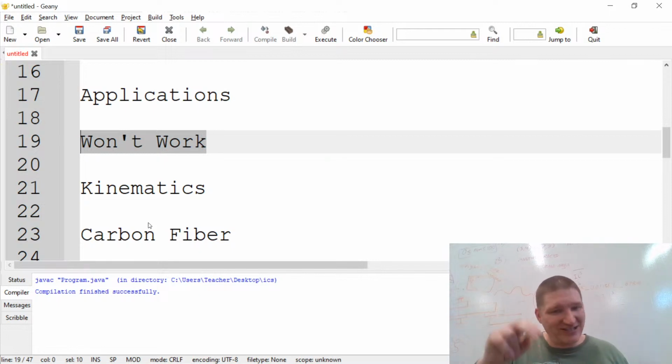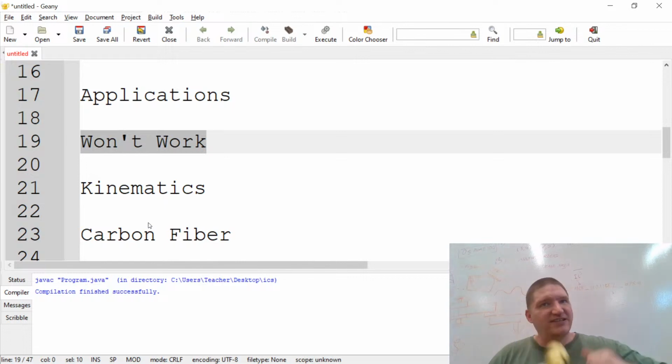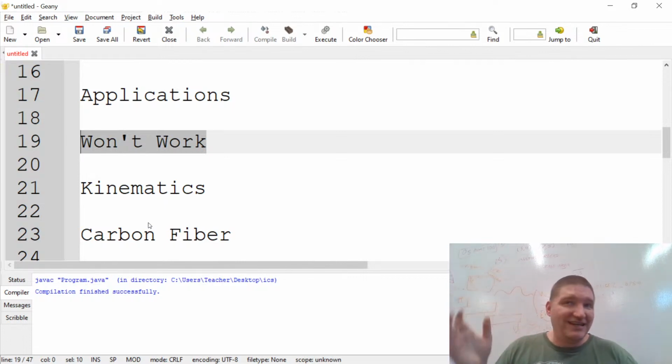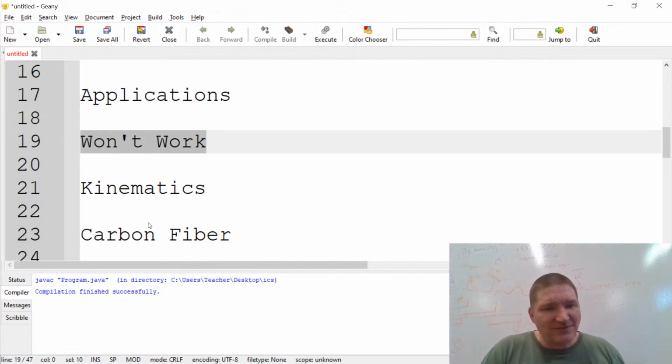If it can keep position, I can make this work, even if it deflects quite a bit when I push down on it. As long as it's consistent under load, I can always set the accelerations down. A lot of people put comments like, hey, you won't be able to do this, if you turn the corner with jerk settings, it'll cause ringing. Lots of complaints about can't do this, can't do that. You just set the acceleration low, set the jerk low. If it can keep a position, I can print with this thing.